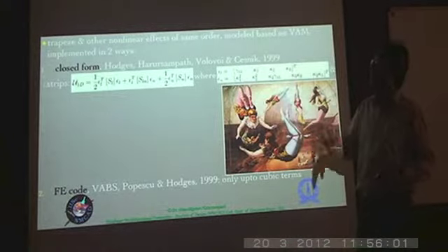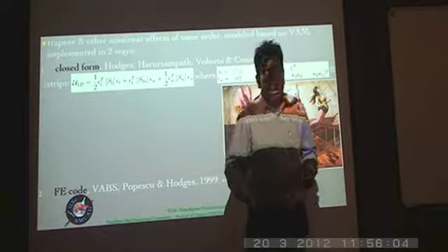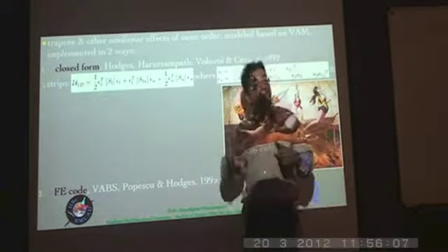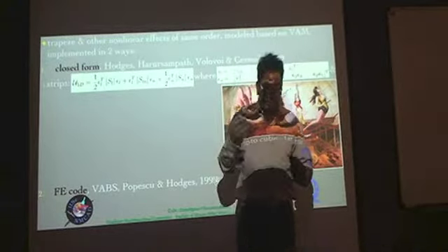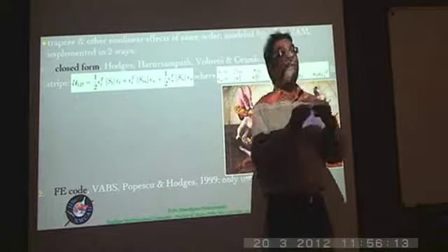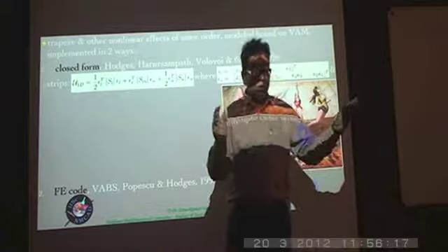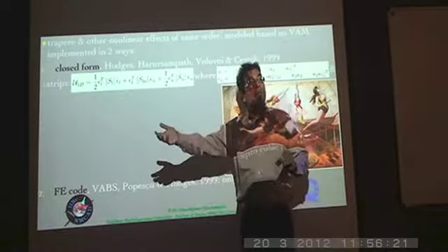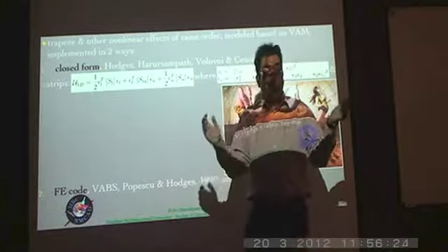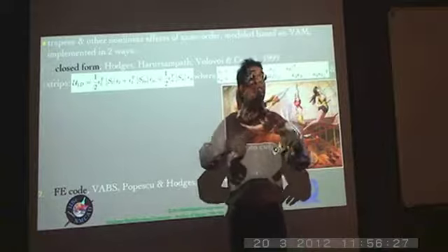If you look at the results for any other type of cross-section, be it a thin-walled open cross-section or closed cross-section or solid cross-sections, you will not have this many nonlinearities. The reason is that you can think of the strip as kind of an interface between solid open cross-sections on the one hand and thin-walled closed cross-sections on the other hand. So it kind of has the complications of both coming into picture.